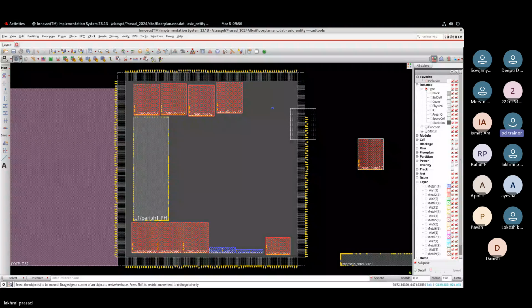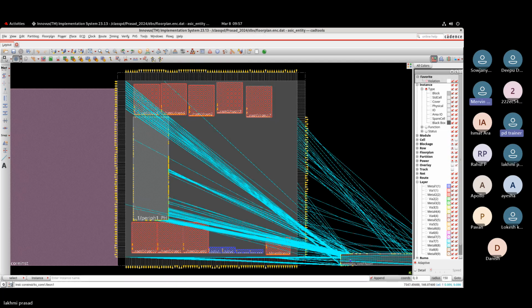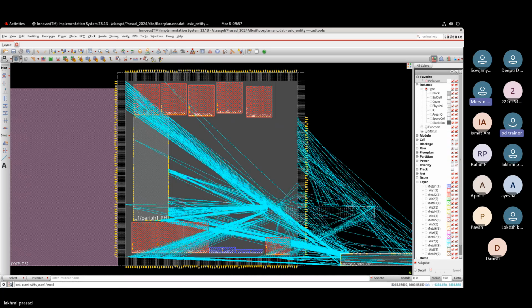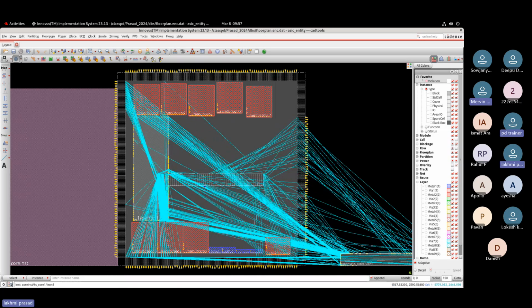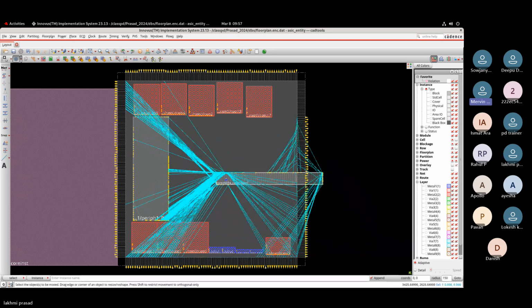How are you trying to load it? Did you invoke Innovus? Yeah, Innovus is in the background already, and I go to the file, restore design. File, restore design. Yes, and I selected the name that we saved, the floor plan in the DBS. What is your file name? In the DBS folder, there is a floor plan .enc.